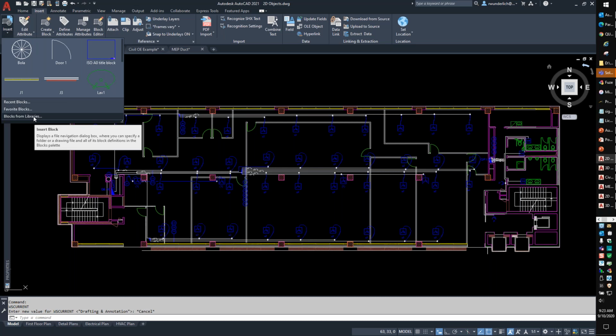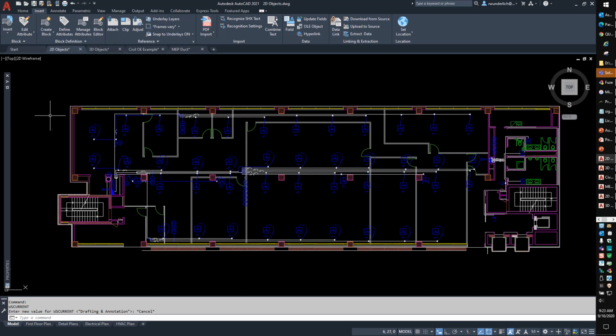So if you're planning on doing architectural type work and you want to use LT or basic AutoCAD, the first thing you need to do is have a block library that has those things in it. Otherwise, you're going to be drawing an outside and an inside wall, things like that. Tool palettes, dynamic blocks, and Design Center work the same in LT. Let me get back to that in just a moment. So as far as windows and door objects, you would need to either create or get those on your own from the manufacturers.